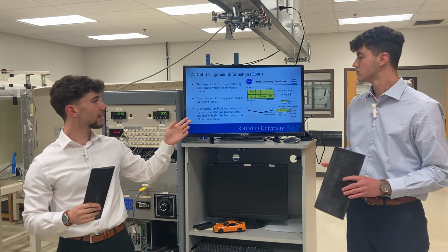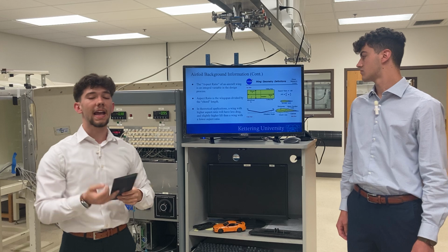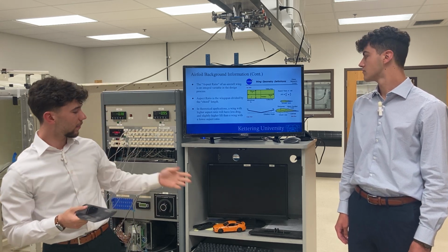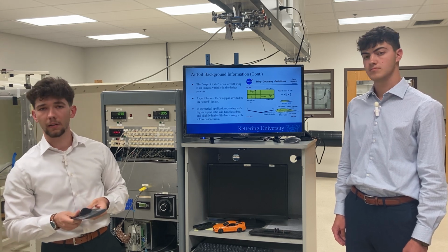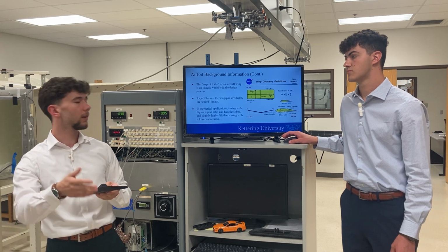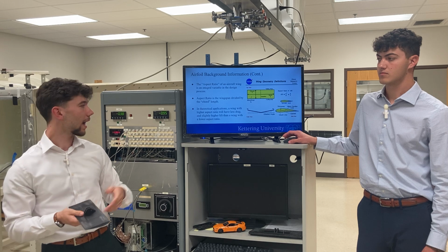And by changing that, you get various different effects over the density, the velocity, and the lift and drag coefficients over top of the foils. So for us, we decided to make two different aspect ratios and see how they stacked up to theoretical applications. In theory, if you have a wing with a higher aspect ratio, it is going to experience less drag and slightly higher lift than a wing with a lower aspect ratio.